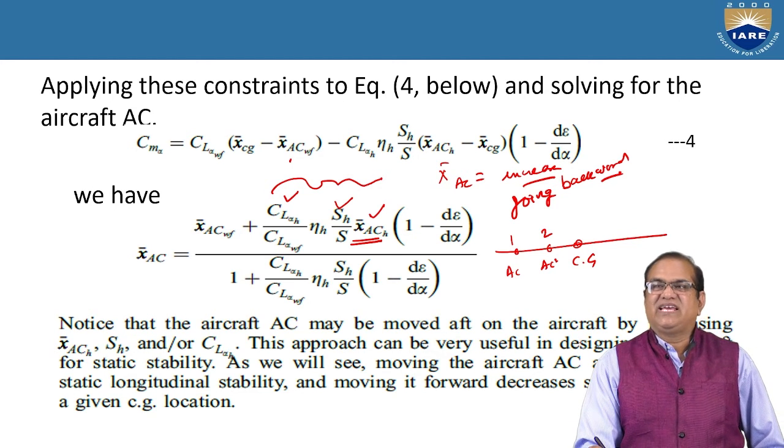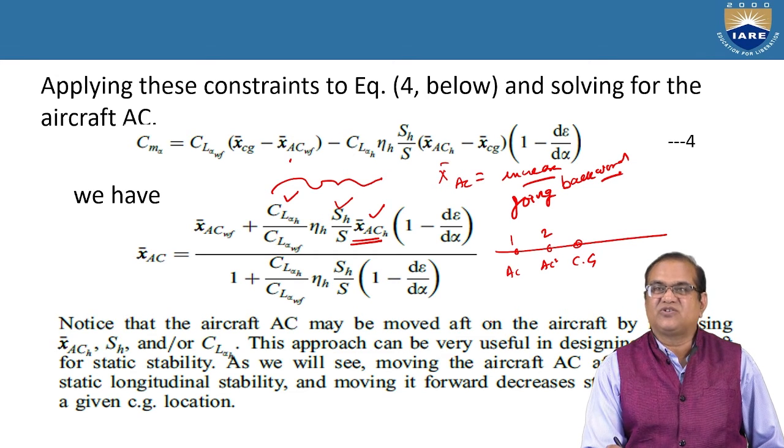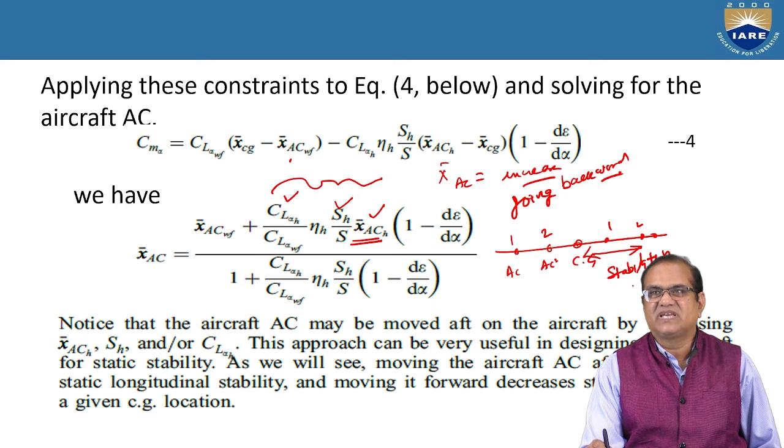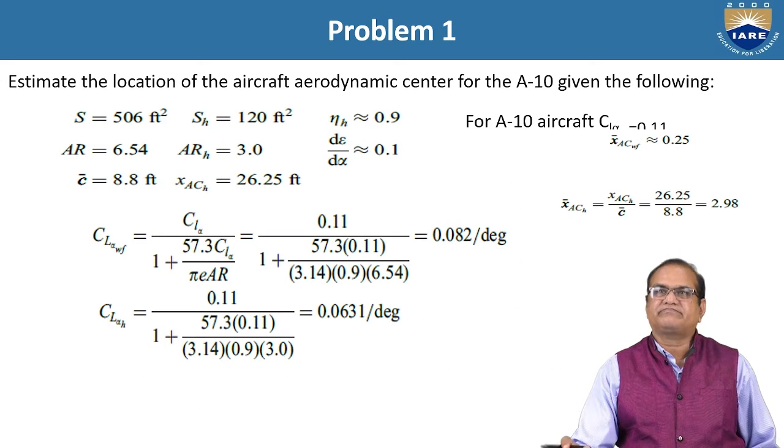Moving the aircraft AC aft will increase the static longitudinal stability. So as the AC goes behind, static stability is increased. So that is the importance of this equation.